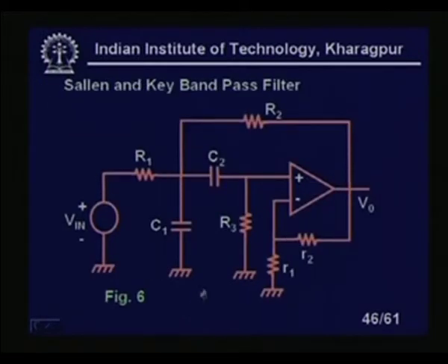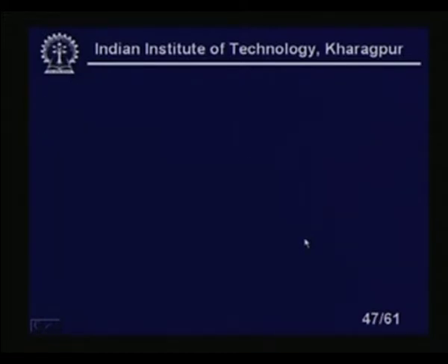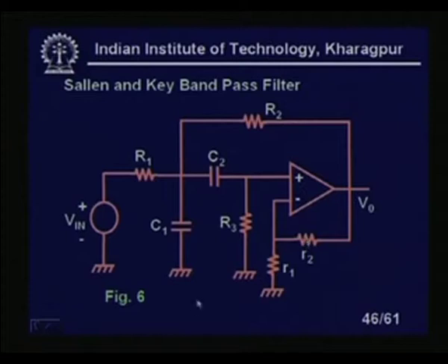So, this is the band pass filter. In the band pass case, we need one more resistor R3, all other resistors are the same as before, but the structure is slightly different, right. It is positive feedback. To make the circuit stable, I have to give a certain amount of negative feedback, right. So, this is our band pass case.